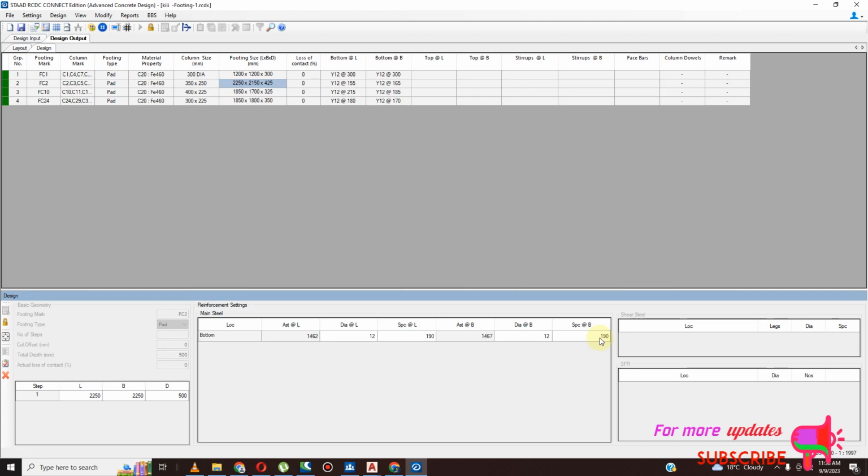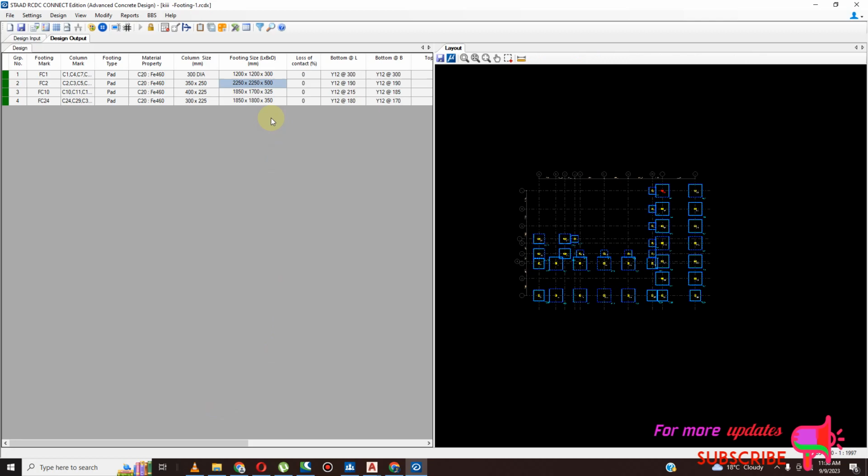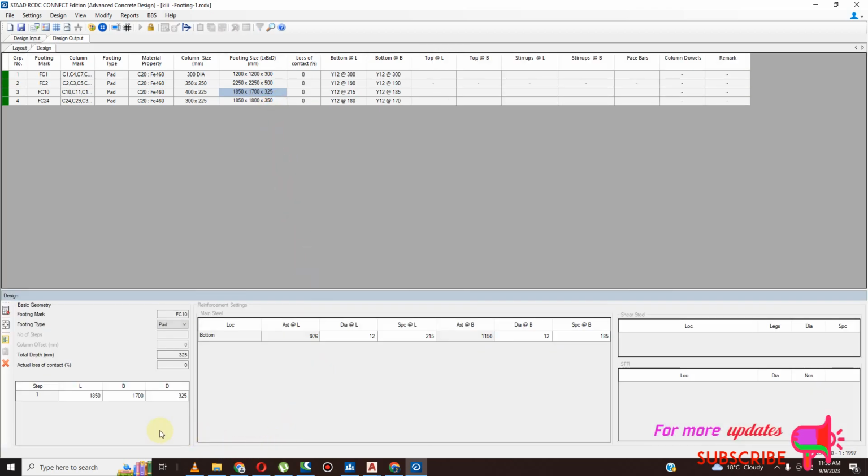Something that can make the construction work easy. So I can accept this now. Right? So I'm going to come to that one, which is 18 feet by 1700, and redesign it. So I'm going to change this one to 400, and then this one I'm going to make it 1800, and this one 1800, and then I'm going to design.